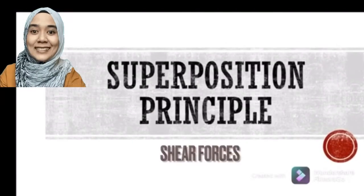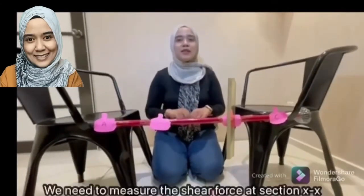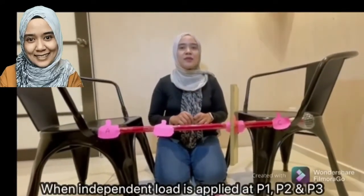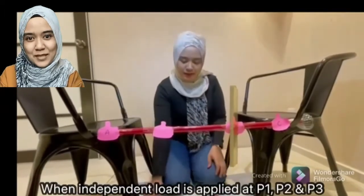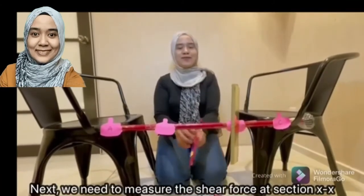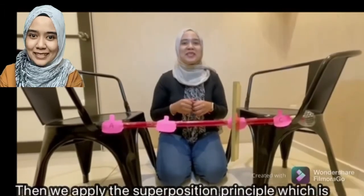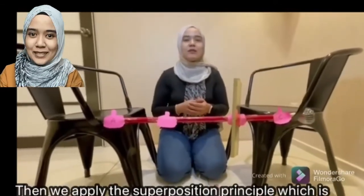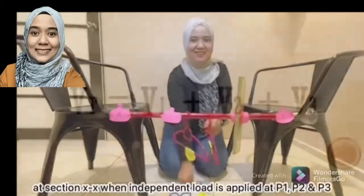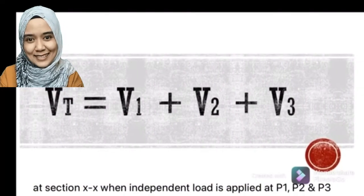Superposition principle. To prove the superposition principle, we need to measure the shear force at section XX when an independent load is applied at P1, P2, and P3. Next, we need to measure the shear force at section XX when all of the independent loads are applied at the same time. Then, we apply the superposition principle, which is that the total shear force is equal to the summation of the shear force at section XX when an independent load is applied at P1, P2, and P3.